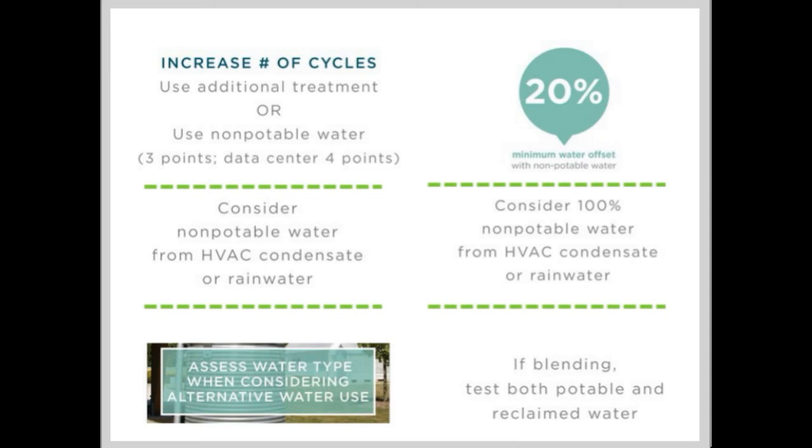Good non-potable water sources include the following: air conditioner condensate, rainwater, steam system condensate, food steamer discharge water, fire pump test water, ice machine condensate. Other factors to consider are ease of transport to the cooling tower and required volume of makeup water.